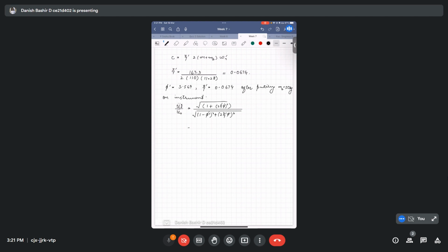So when we are substituting it here, we are getting transmissibility as 0.0416. Okay, and we will get the desired transmitted acceleration u naught double dot transmitted as, because u naught double dot is 0.1 g, it will be 0.00416 g, which is less than 0.005 g tolerance.